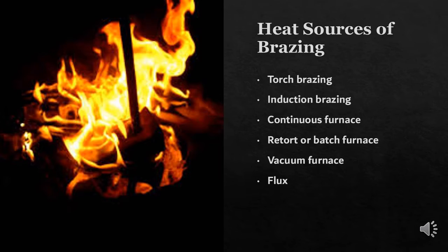Torch brazing means a heating source supplied by a fuel gas flame. Induction brazing means the electric coils are designed for specific joint geometries, and are used to heat the part and the brazing filler material until the liquid metal flows via capillary attraction into the joint itself. Continuous furnace means conveyor belts transport the pre-alloyed components through preheating, heating, and post-heating zones, where the brazing alloy reaches temperature, then resolidifies during cooling.